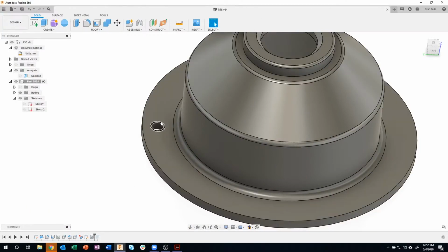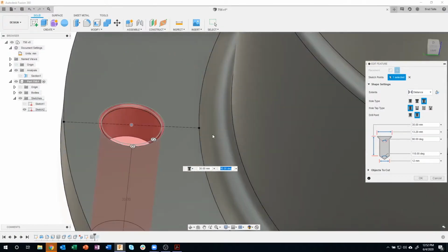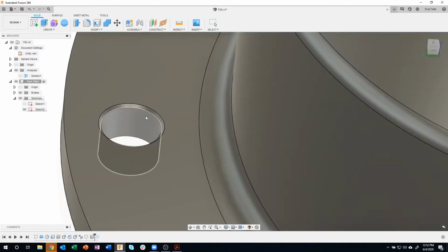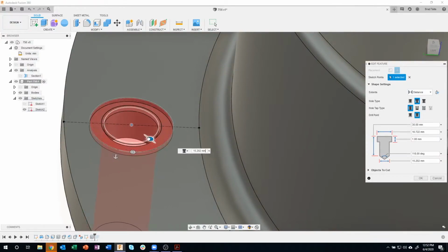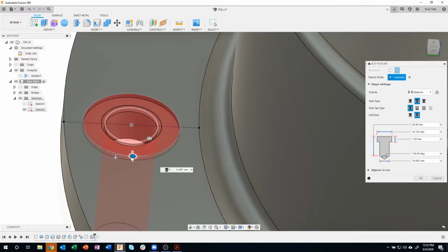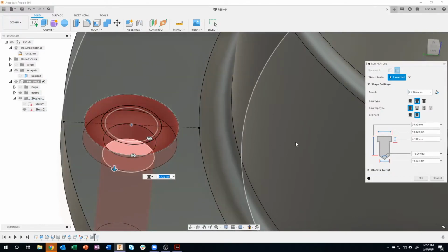that we want this to be a chamfered hole or a counterbore hole or whatever, it is much faster to come back and edit this feature and say, I want that to be a countersunk hole. Let me just say okay, and you'll see, sure enough, it's countersunk. Or I want it to be a counterbored hole, and we can specify what size counterbore it's supposed to be, all that kind of stuff. I picked the wrong one. But you get the idea, okay?